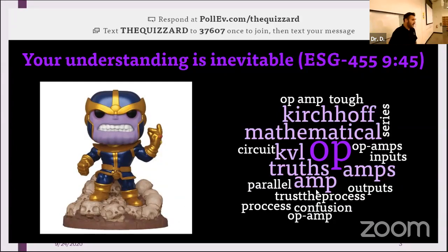I think most of the confusion probably comes around when do we use the voltage law versus when do we use the current law, right? How do you know which one you're going to need? Well, if you don't have any nodes in a circuit, if you have a simple RL circuit like we had in our very first example, there's no nodes, right? So if you don't have a node, then KCL is not going to get you anything that's interesting, and so KVL is there, right? So I guess the general rule of thumb would be see if you have a node. If you have a node, then you can use KCL. If you don't have a node, then don't bother with it.